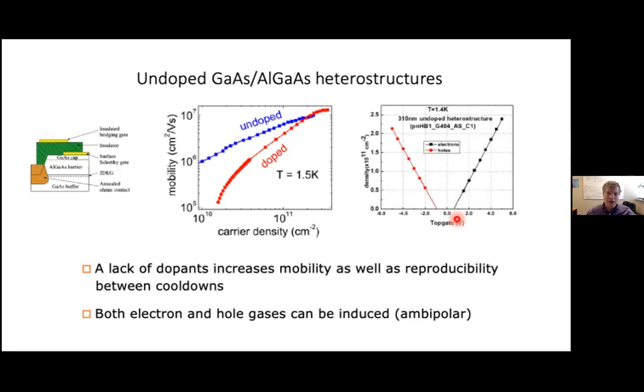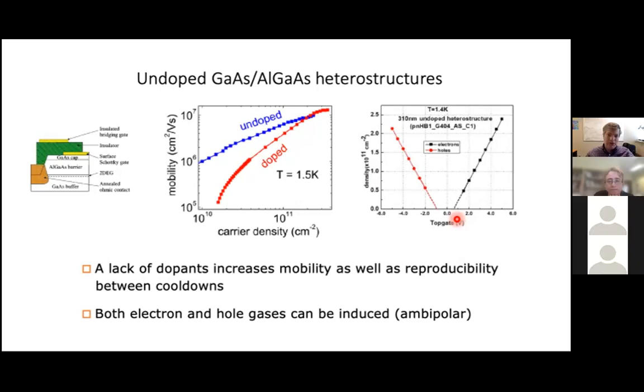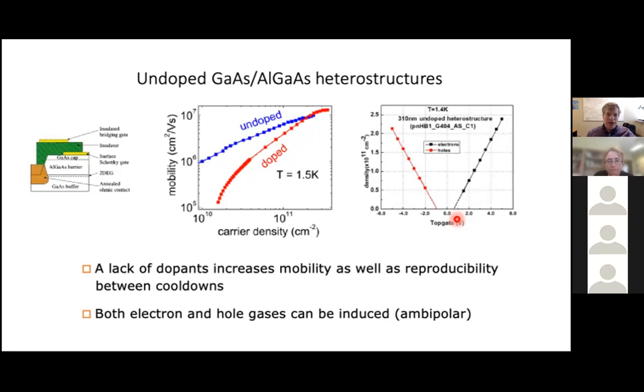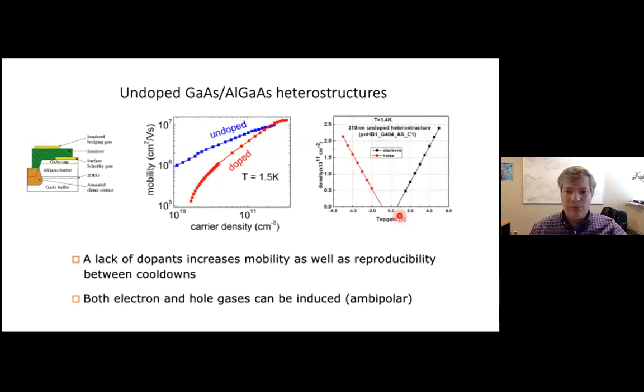And so therefore, you need separate N-type and P-type ohmic contacts. But other than that, it really is just as simple as changing the top gate voltage to get electrons, an N-type semiconductor, or holes, a P-type semiconductor. So that means that we can make truly ambipolar devices with these gallium arsenide 2DEGs and 2D hole gases. And that opens doors to a lot of exciting things.